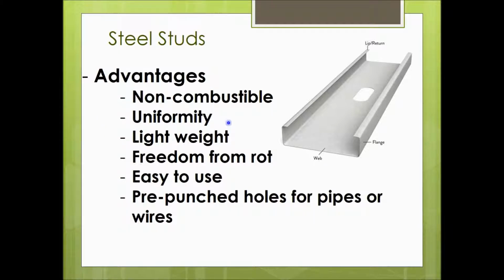There are no defects. They're lightweight. They don't rot, but they probably would rust after a period of time if they were exposed to the weather for long enough. They're easy to use, and finally, they have pre-punched holes for pipes and wires. Okay. So that would keep your mechanical contractors, plumbers, and electricians from having to drill holes in the studs to get wires and pipes through.